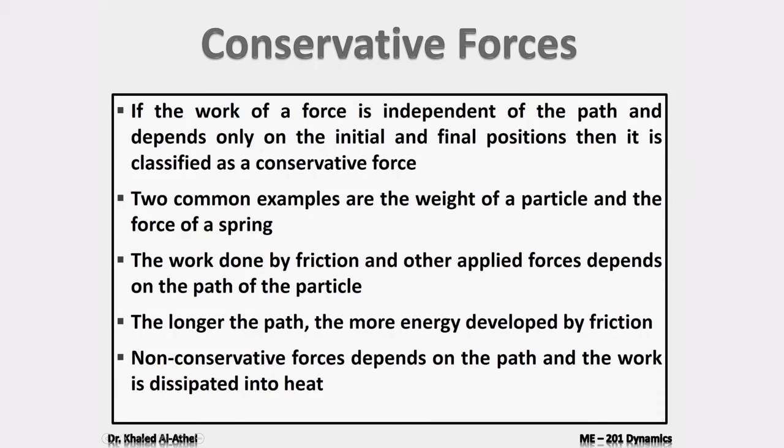If the work done by a force is independent, and this is the main point, independent of the path and depends only on the initial and final position, then it is classified as a conservative force. Meaning, I do not care how you went from point 1 to point 2, I only care what is the location of point 1 and what is the location of point 2. An example of this would be the weight of a certain object or a particle and the force of a spring. These are the two main conservative forces that we deal with in dynamic problems.